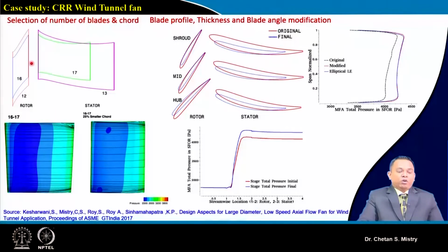If you recall, this gives us an idea of a lesser number of blades and a larger number of blades for the rotor. We must realize the passage between two blades is the diffusing passage, and it follows all the rules we have discussed in terms of length of the diffusing passage, diffusion angle, inlet area, and outlet area.